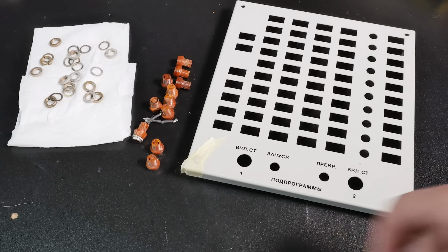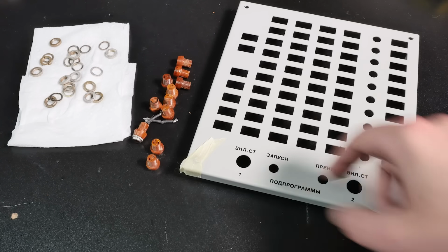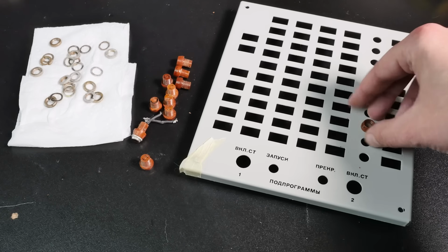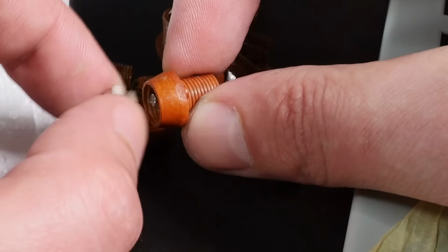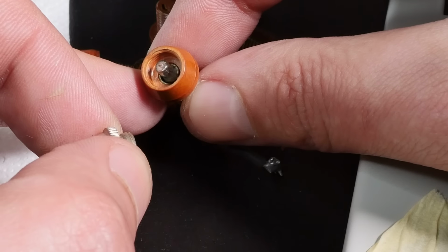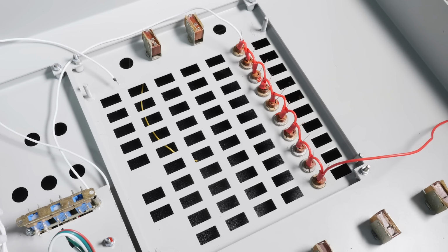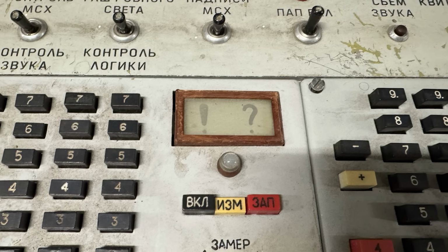And before we installed them inside the housing, I needed to make a few more things. First, program indicators, because they are the only components secured directly on the front panel. In the original console, inside were small incandescent lamps covered with lenses. The cool thing, however, is that it is possible to install warm white LEDs instead. It will look the same, but will consume significantly less current. Next, we needed to reproduce the error and attention indicator, and that was kind of a tricky one.